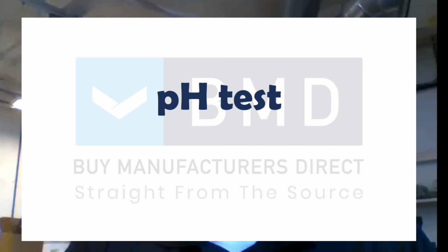The biggest thing that a lot of people miss is pH testing. That gives you an idea of what that concrete is exposed to and what you're dealing with. Concrete is an alkali material. It has to be. If you take the alkalinity away and you take too much moisture away, it goes back to its original state, which is basically sand and cement. But as a hard concrete material, you do want a certain amount of moisture there, and you do want a certain amount of alkalinity. Now, that's not to say that it can't get out of whack. If the alkalinity goes below a 9 or above a 12, you're running some risk of problems with the concrete.